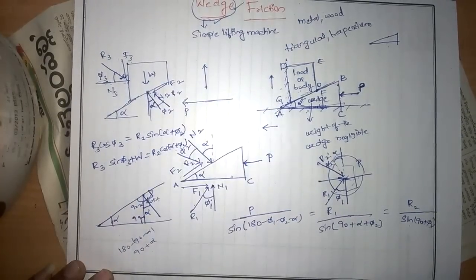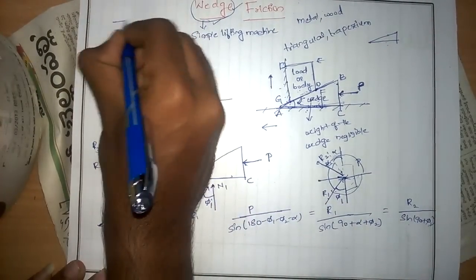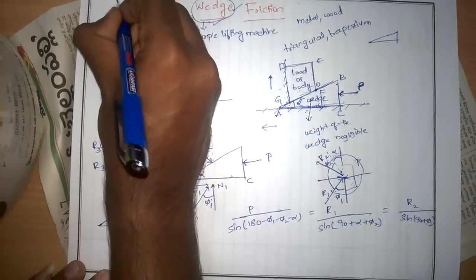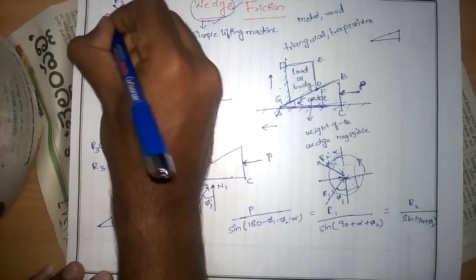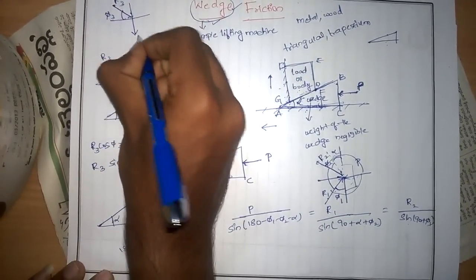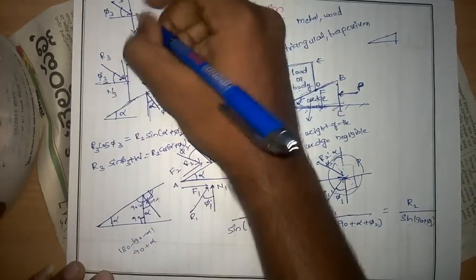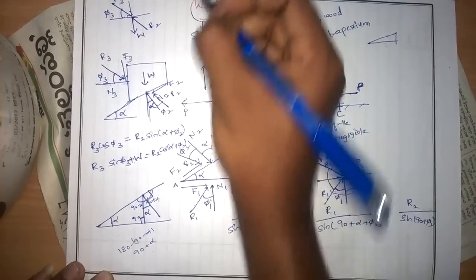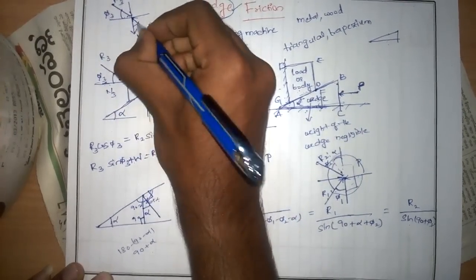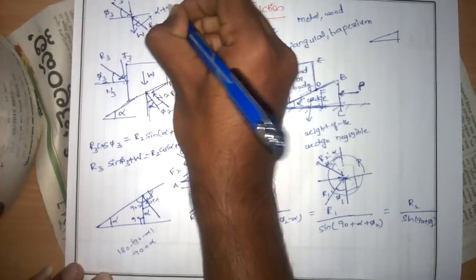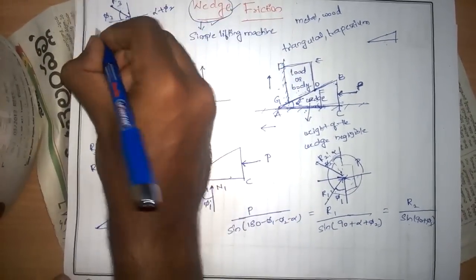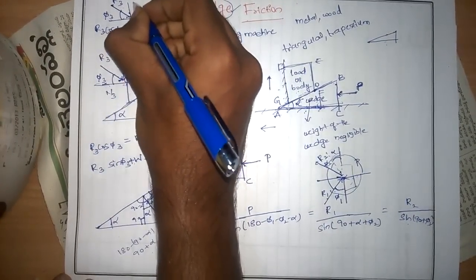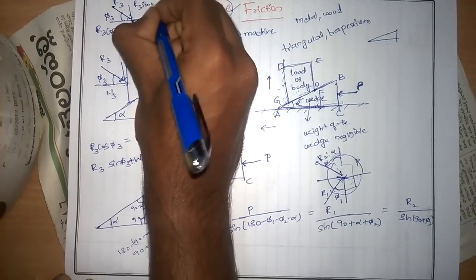It is a little bit confusing, I think. If we draw this, here is R3, which is making an angle of phi 3, and a load W is acting, and there is another force R2, which is making a total angle of alpha plus phi 2. If we resolve this, it is R3 cos phi 3, and in the downward direction R3 sin phi 3.